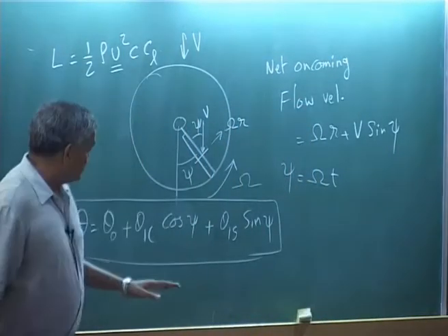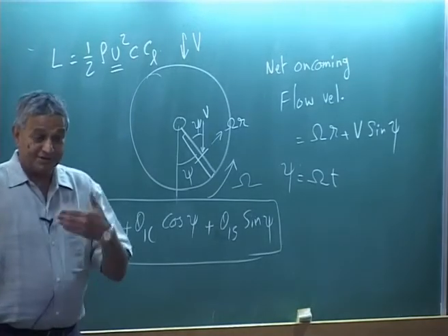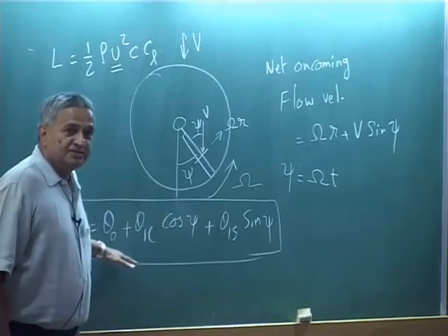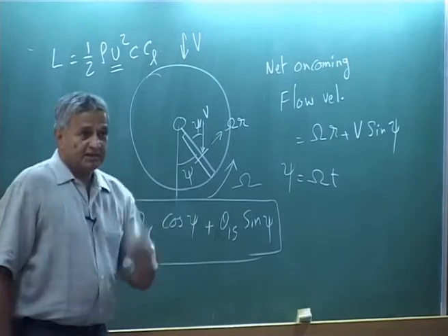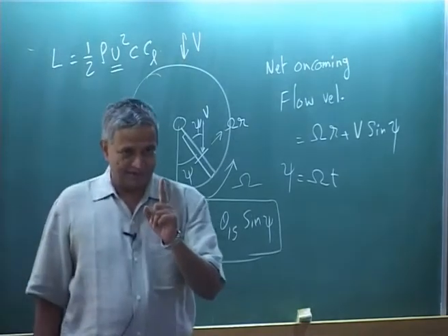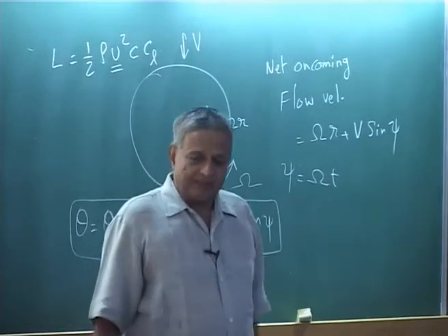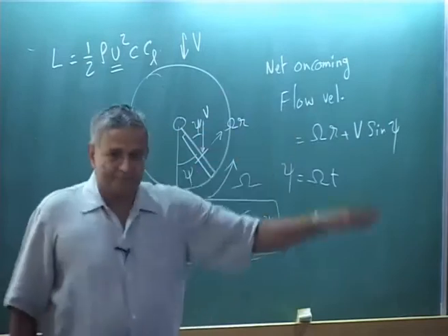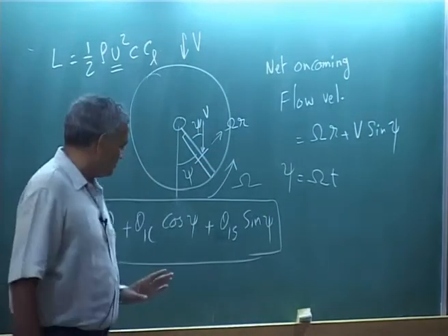Now, that is why you see the swash plate mechanism which is introduced in the blade is essentially to change the blade pitch angle once in a revolution. Please understand, that is why 1 per rev, you do not change 2 per rev, 3 per rev. Later we will see there is something called higher harmonic control that will come maybe towards the end of the course, just for a description of that part.